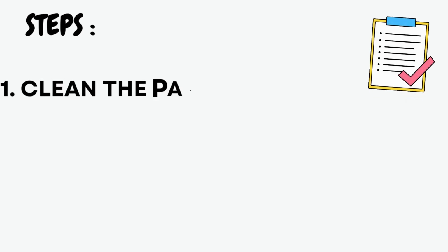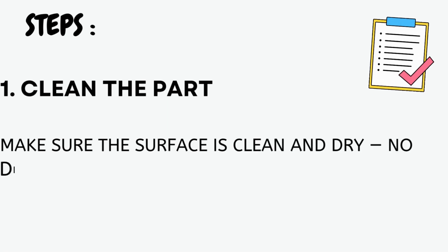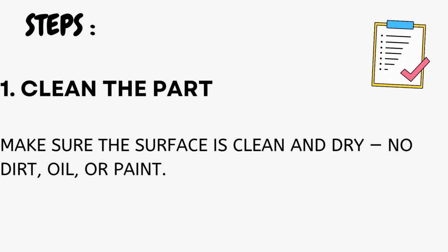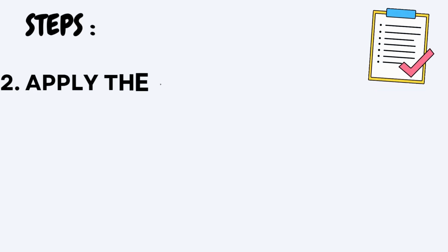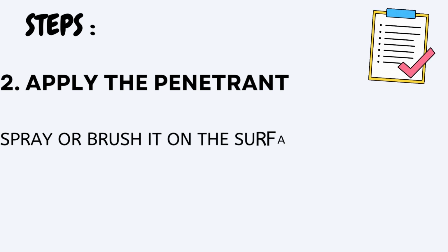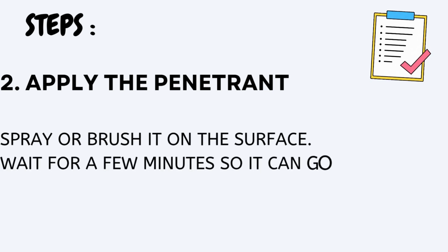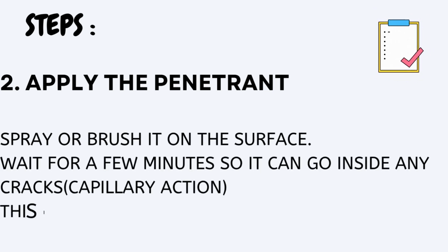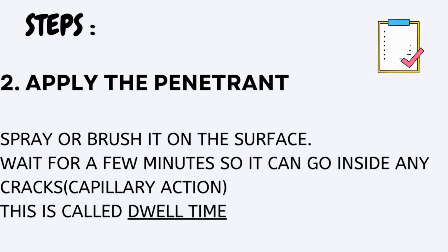1. Clean the part. Make sure the surface is clean and dry, no dirt, oil, or paint. 2. Apply the penetrant. Spray or brush it on the surface. Wait for a few minutes so it can go inside any cracks. This is called dwell time.